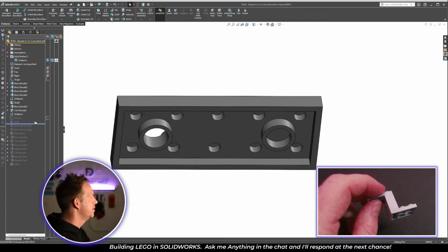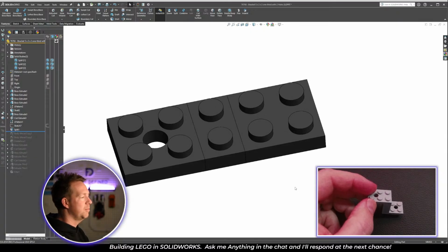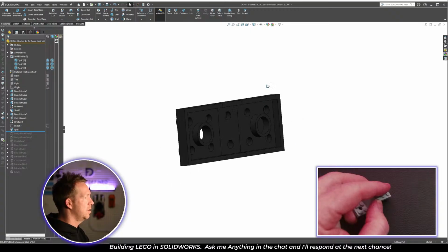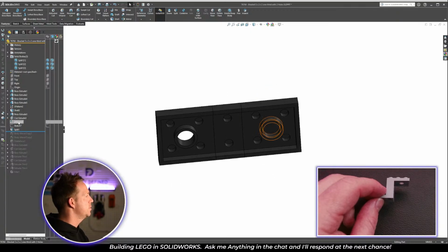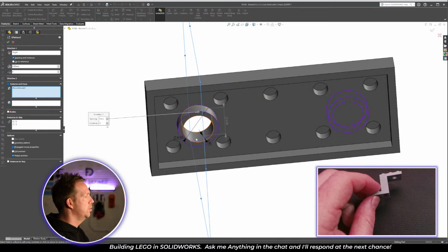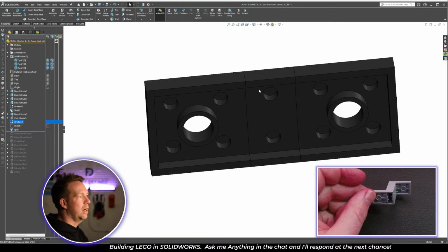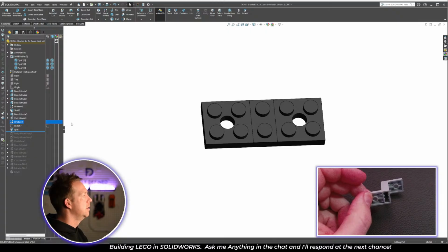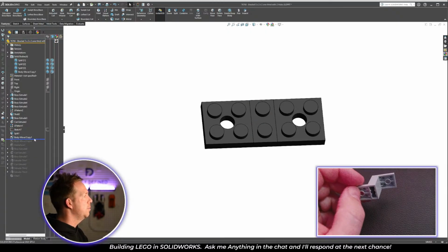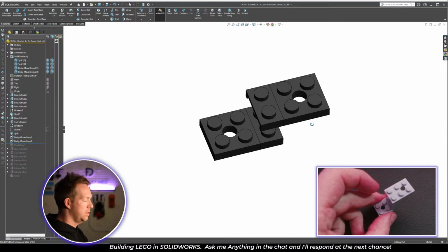I don't mind. Right, so this one was then, I'd split the part. So this is where I think I should do that second cut at the same time. So I'm going to edit this feature, the linear pattern feature, and include the cut. So I'm going to jump in the tree here, grab that cut extrude as well, because the two holes carry across. So I'll get that in the pattern. And then when I move this body up here, it's going to have that feature for me.